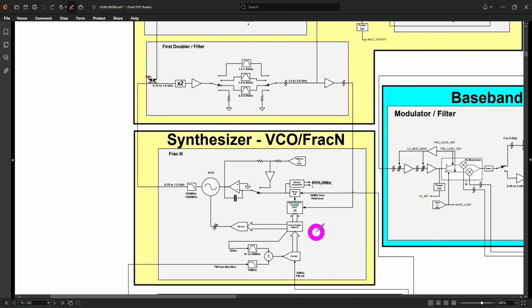All right, back to the block diagram we go once again. So we have verified the VCO as well. So most of the things are verified. Unfortunately, we're getting closer and closer to the custom chips from Agilent, and that's going to make this unrepairable if we can't replace them. So let's take a look at what is left. So we know that it works in some frequency ranges. So this custom divider circuit, the phase detector, they do work in some places, but just not in all other frequency ranges. So perhaps this divider's ability to actually divide in a fractional-N mode around the frequency of, let's say, 1.4, 1.5 gigahertz, it just doesn't work anymore.